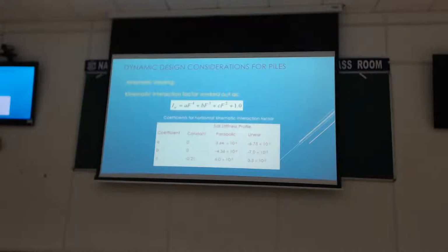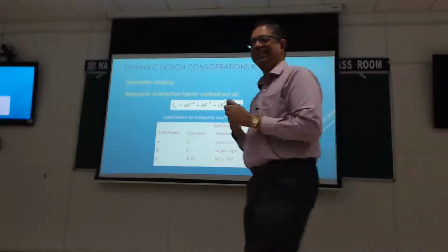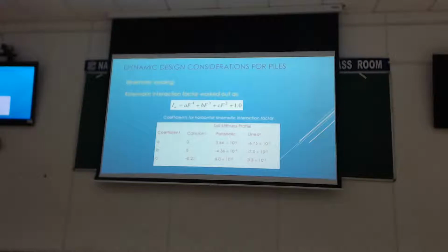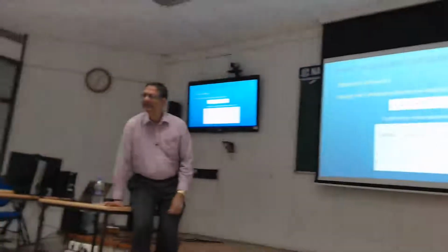So I heard three answers. Both, kinematic, inertia. Nobody said none. Can you justify your answer? Most of the experiments say inertial load is more detrimental than the lateral spreading of the flowing soil. Yeah, that is true. We believe that. Can you see situations where the kinematic loads can dominate? Like liquefiable soils.